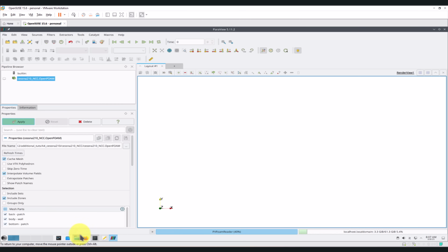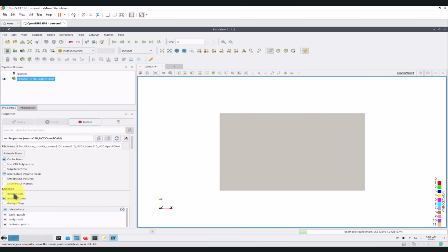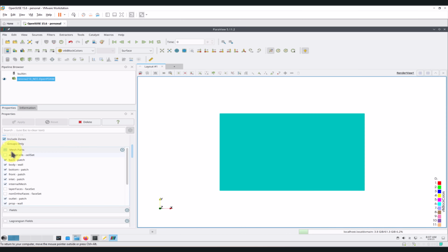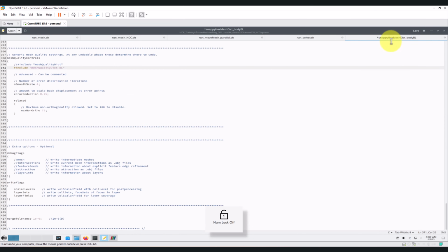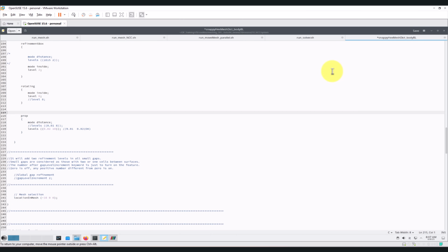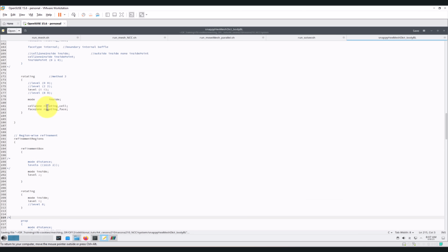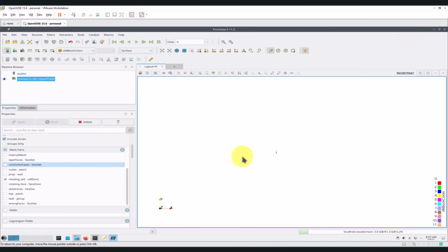Remember that in paraview, when you use this option, you have this plugin there. You can read the steps. And what I want to show you is that all the steps, now that we're computing, even the bad quality cells, you can access that and visualize that. But what I want to show is this one. Recall that at meshing time, we created these regions there. Here, you can access those regions.